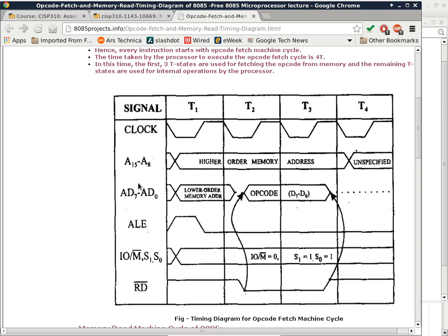So it's fun to do that, but you can only do so much with this approach, because the precision of using a Sharpie to draw out your traces is kind of limited. So a lot of components these days have such a high density that you really can't do it easily. Okay, and then if you go to Fry's, they sell special kinds of things that you can glue onto the circuit board in order to make what we call the land patterns of smaller pins for smaller components.